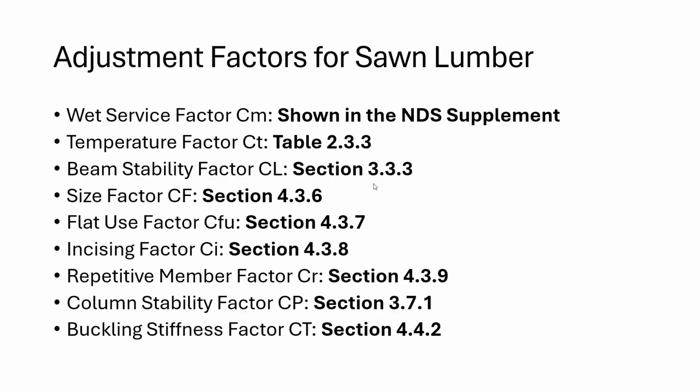So wet service factor, CM, that is dependent on your environment condition. So if you have a wet environment or a high humidity environment, you're going to adjust accordingly. And that's shown in the NDS supplement, which I'll talk about in a second, because it is species dependent on how moisture is absorbed into the wood itself.